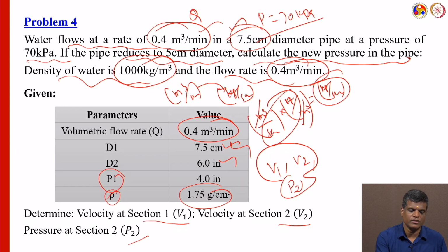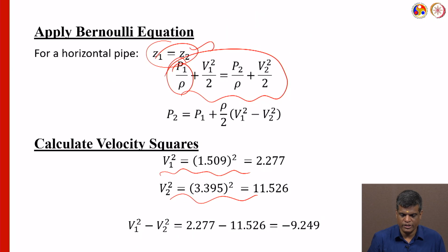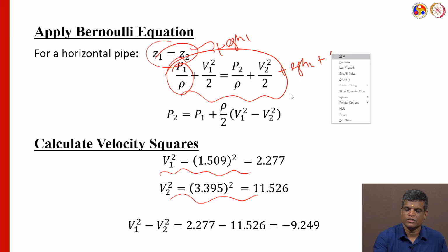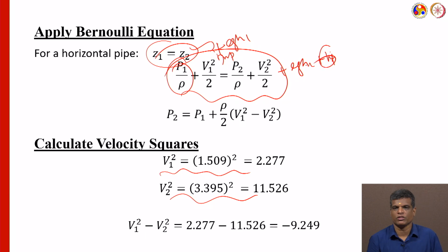So, this problem is very easy, it is not very tough, but you only have to use the conversion from volumetric flow rate to mass flow rate, and then we have to use the Bernoulli equation. In the simple Bernoulli equation, we can add rho g H1 and rho g H2, and sometimes if you add the efficiency of the pump, eta Wp, we can add it here, and we also have to add HF, the friction loss, if friction head is there. So, we can add it here.